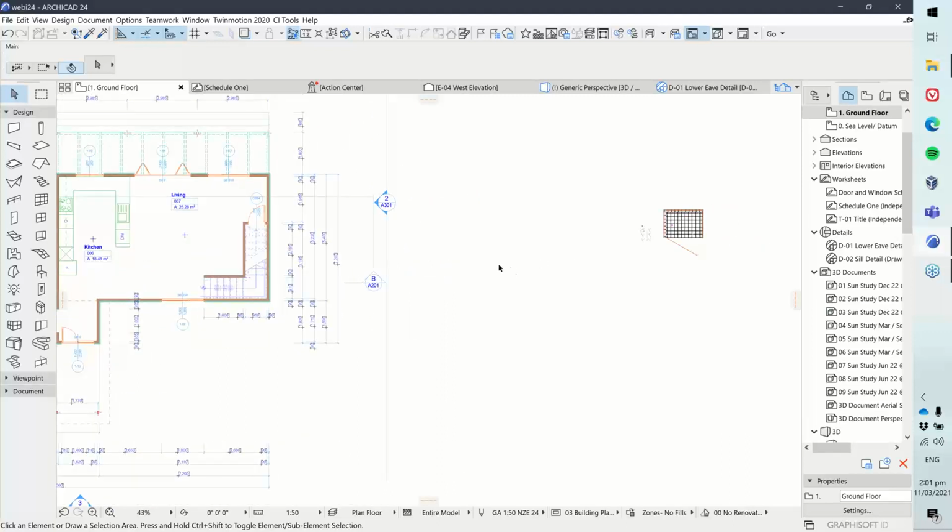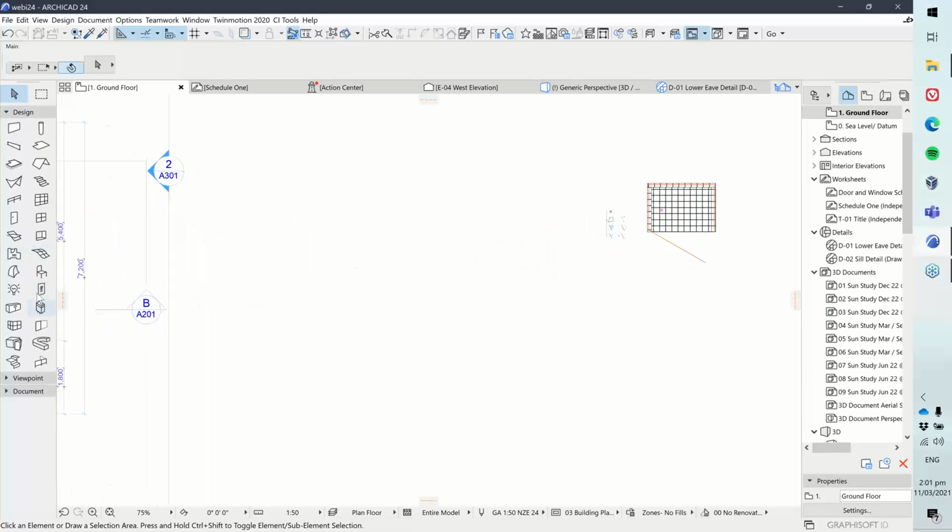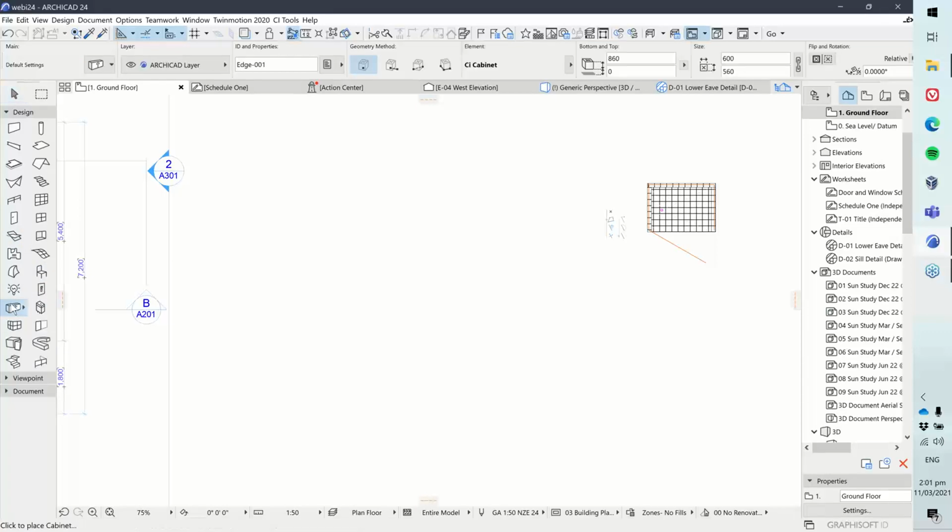One person is asking about how you cut a hole in the cabinet tool, which the way that I showed, I think that was while I was showing the floor frame with the contour in the middle of it. That's not the way that you cut holes in cabinet bench tops, unfortunately, because the way that we make it work is we just let the user do it using the solid element operation tool, because that way gives you exactly the size that you need for the element that's in it. You don't have to resize the hole on your cabinet if you resize the sink and that sort of thing. So I'll just very quickly show you how we do that if you haven't seen it before.